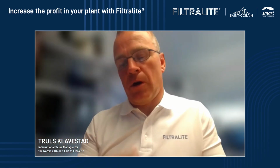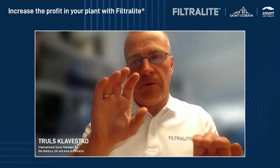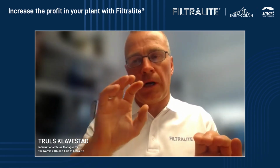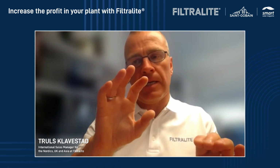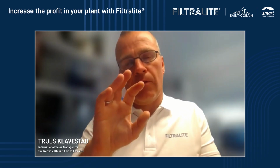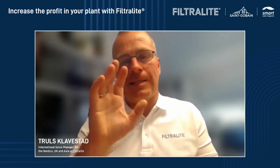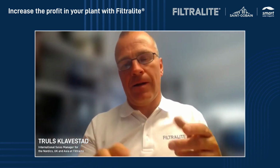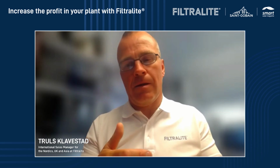But you can also say that if you have a lower grain size of anthracite and a bigger one of Filtralite, you can store much more suspended solids. But what will happen in this case with the bigger grain size? That will have an influence on the water quality, because you will probably have better water quality with anthracite. So there's always this balance you need to keep in mind.